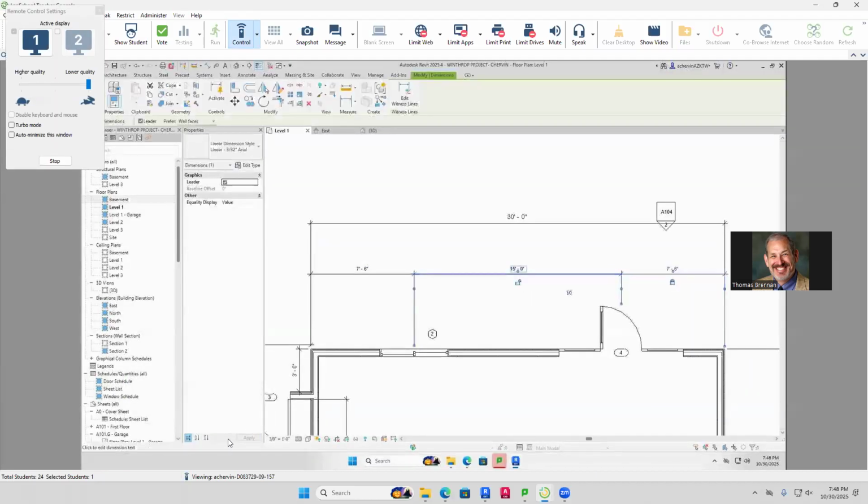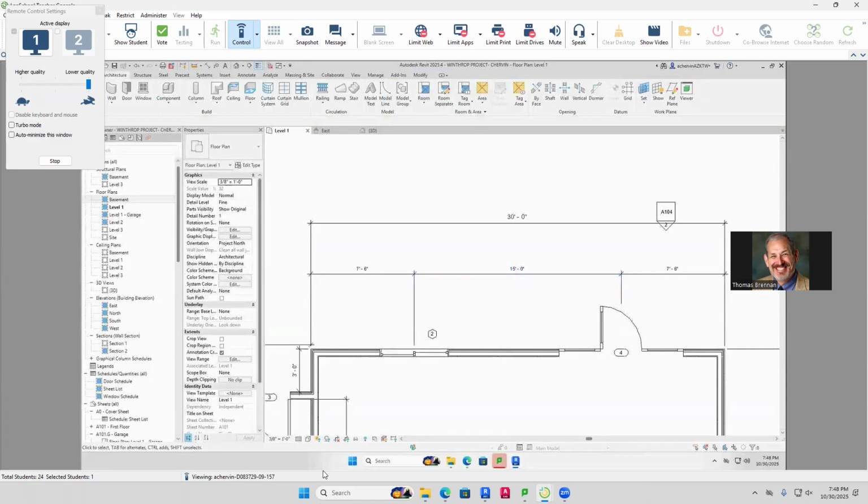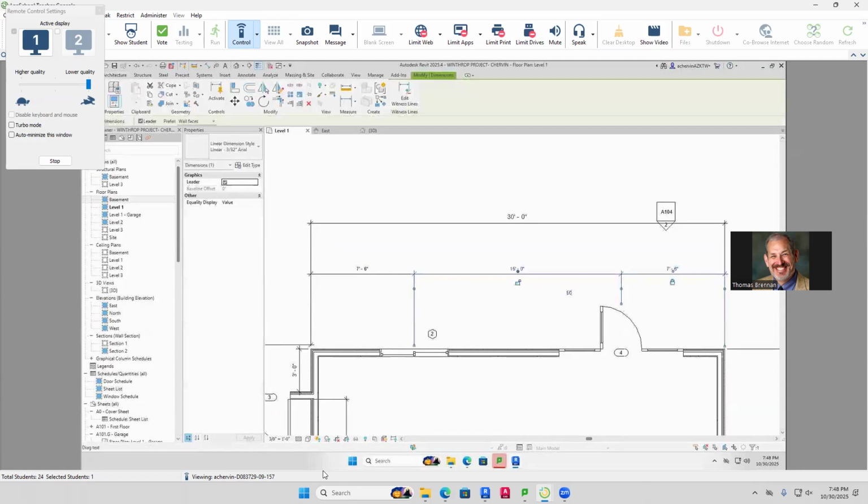Okay, take a look. What's going on? And then get rid of the 16 measurement. You can't? Oh yeah. Let me show you a trick here. Press the escape key. Hover your cursor over the 15-foot dimension, right over the text of it. Press your tab key. Now click on it, and then press your delete key.